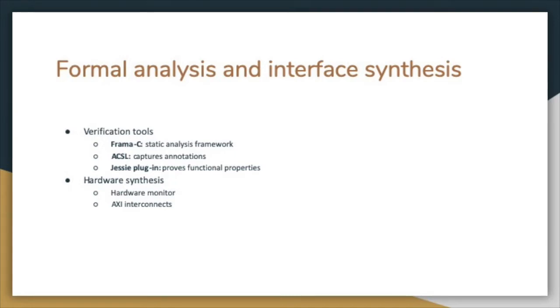As for hardware synthesis, after formal verification, the hardware monitor's software-defined functions were implemented in the programmable fabric using a C synthesis process. For the junction box, a trivial C function was used to create the AXI interface adapter for the AXI interconnects.